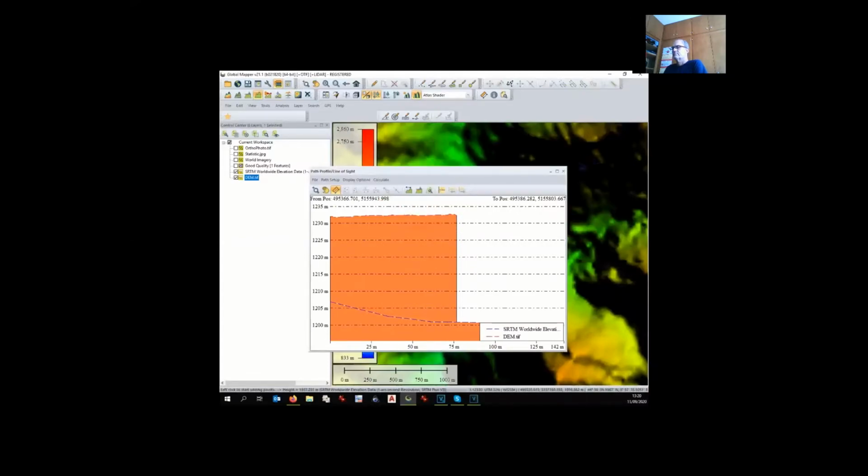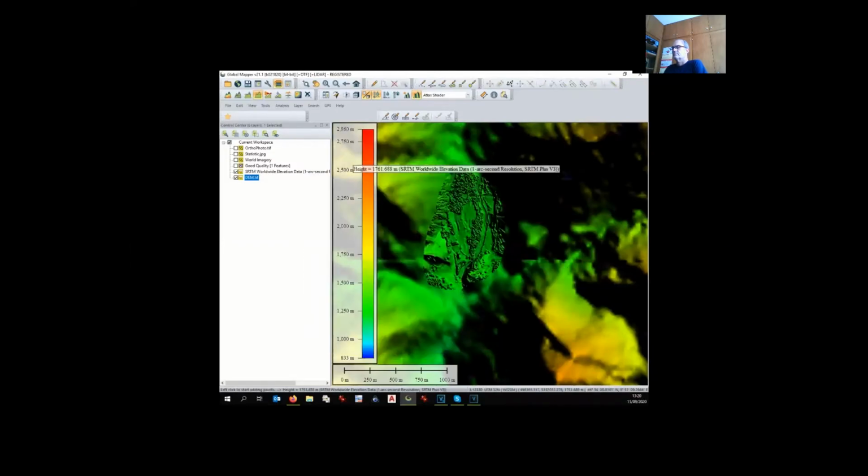It means that the absolute elevation of our model is around 25 meters higher than the digital elevation model of the internet. Why is that? This happens because the absolute elevation of the drone is not very precise, and as far as I know, there is no means to calibrate this elevation unless you use ground points. If you use ground points, you increase the quality of the elevation of your model.